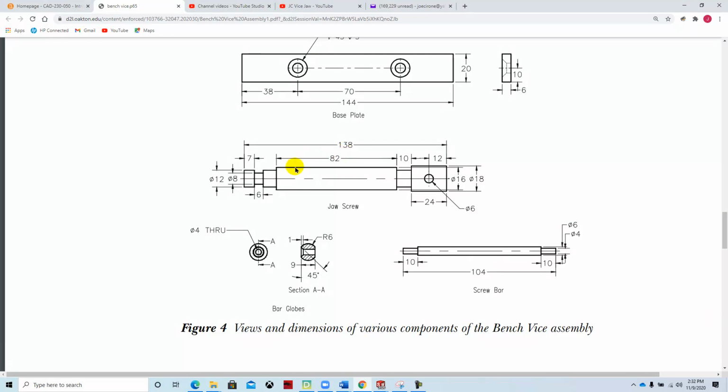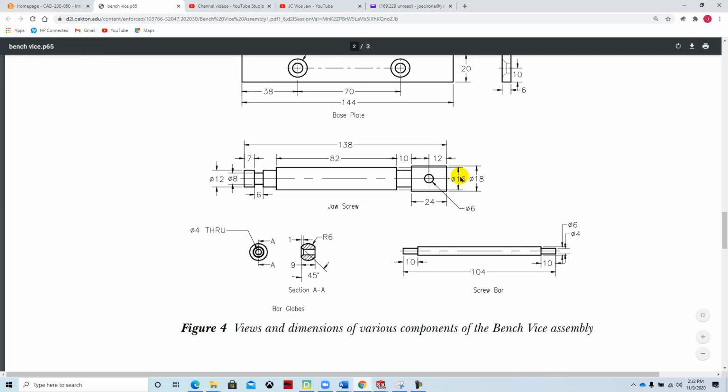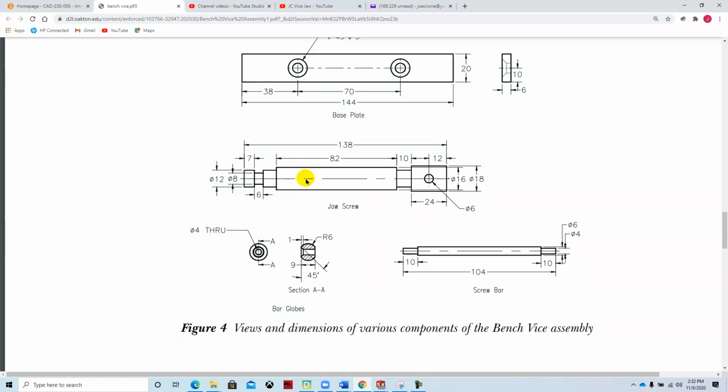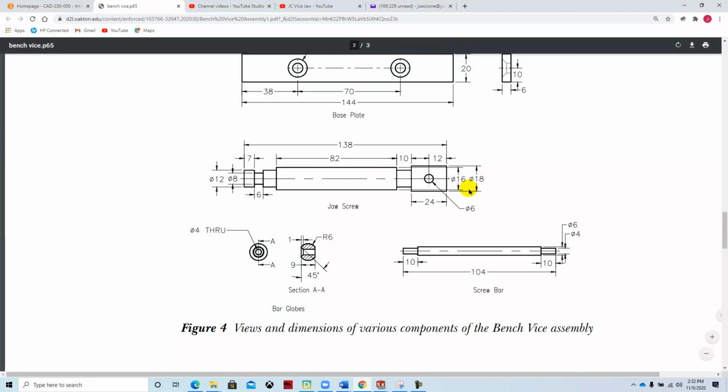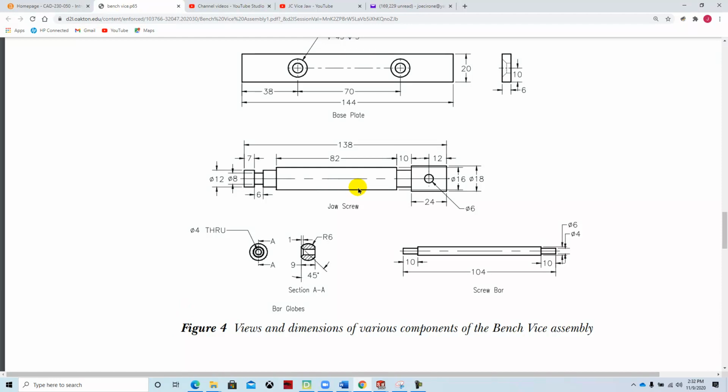If we look at the diameter values, we've got a 12 millimeter diameter, an 8 millimeter diameter, and a 16 millimeter diameter. That's the overall length of it here. This part we could actually look into using the Thread Wizard and cutting a 16 millimeter thread on, and actually try printing it with threads. Everything else is pretty straightforward.